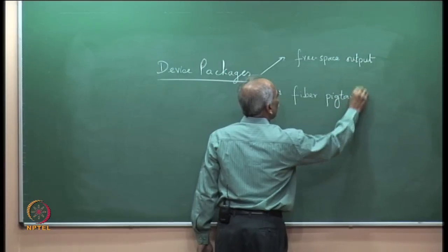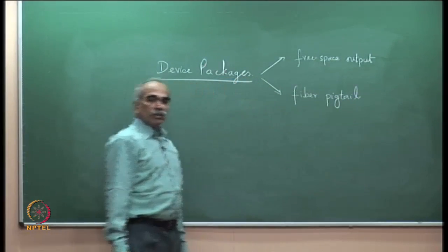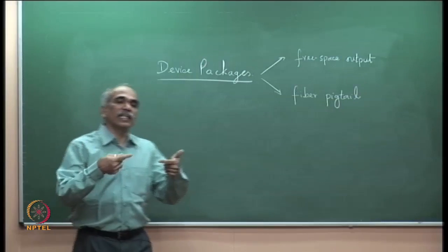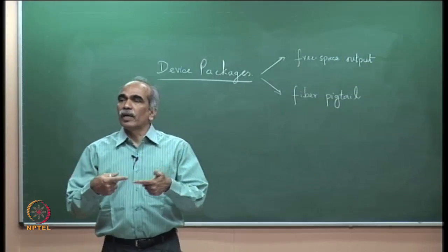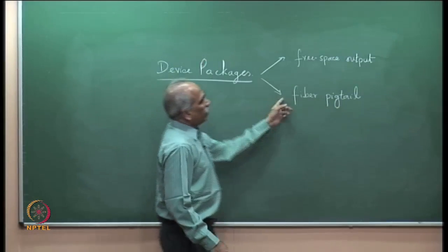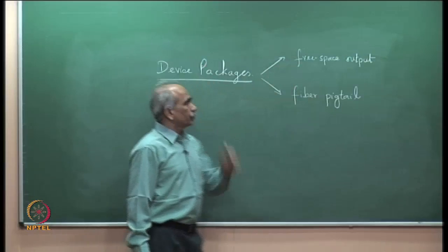Almost all the laser diodes used in communication are fiber pigtailed laser diodes, because you can directly splice it to the fiber which is on the line. Fiber pigtail or free space output.